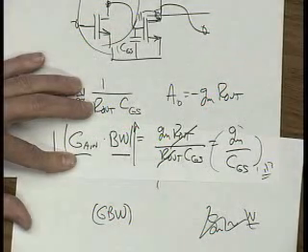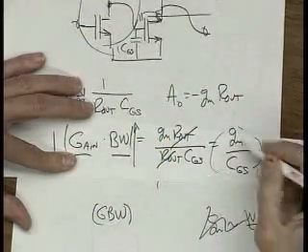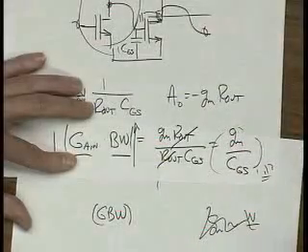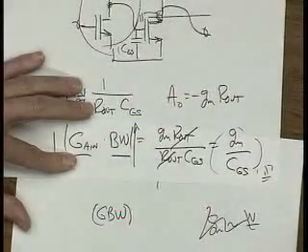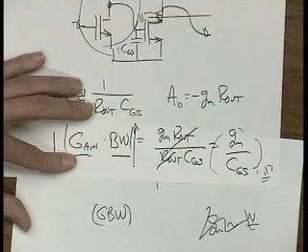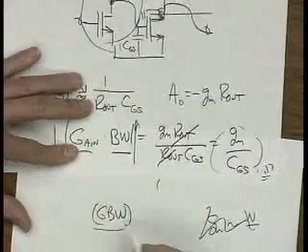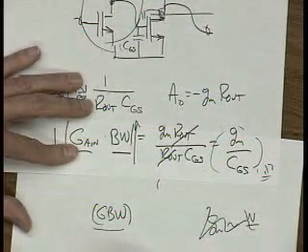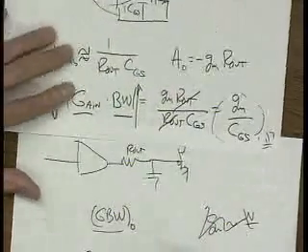The next generation will be 90 nanometer, 0.09. That increases this number a lot. So that's a very strong function of the line width, the minimum channel length you have in your device. That's kind of fun. So it's fundamental to the process you have available to you. You have 0.13 micron as the process you're working with, so you're kind of stuck with this gain bandwidth number. Let's call that gain bandwidth for whatever process you have, GBW0.